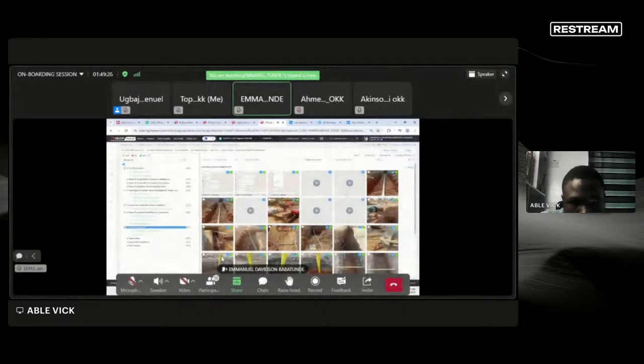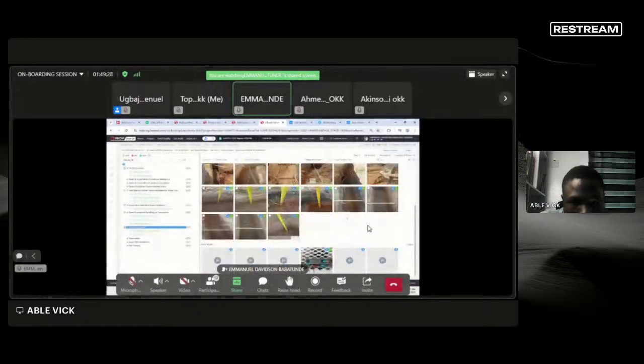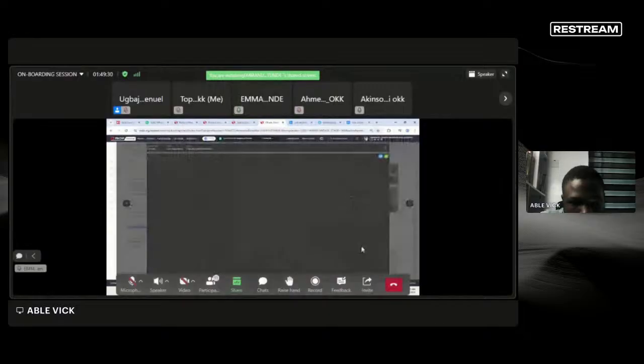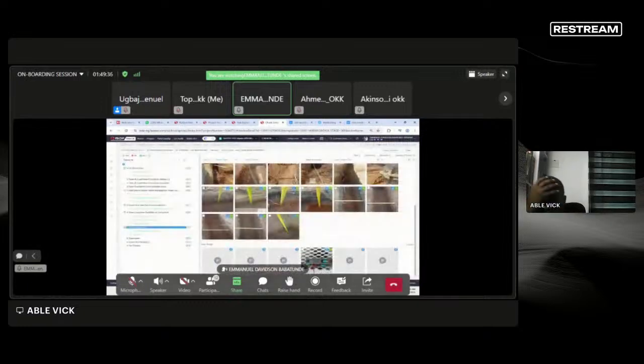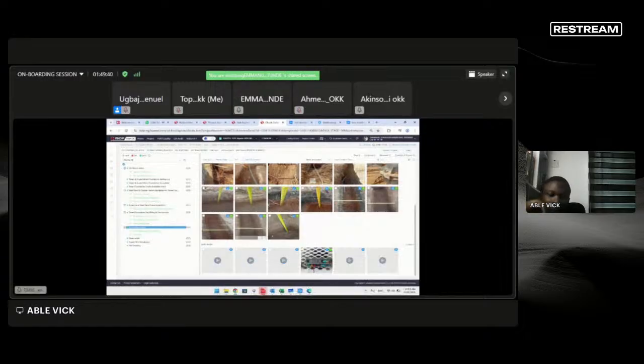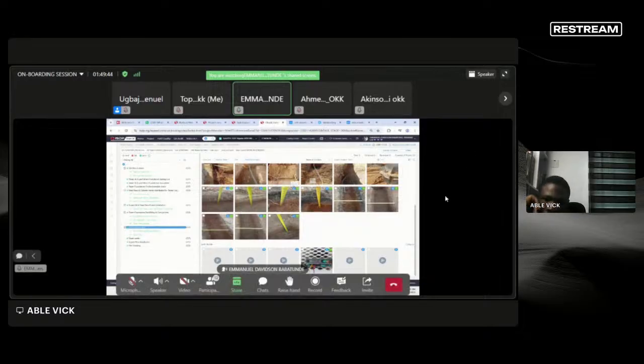To drive it into the ground like that. Then after the earthing is installed, you can commence your backfilling. If all the earthing system has been installed and the bolts and nuts have been connected, you can commence your backfilling of what you've excavated and run your earthing test. For your earthing test, at least 3 points should be tested.